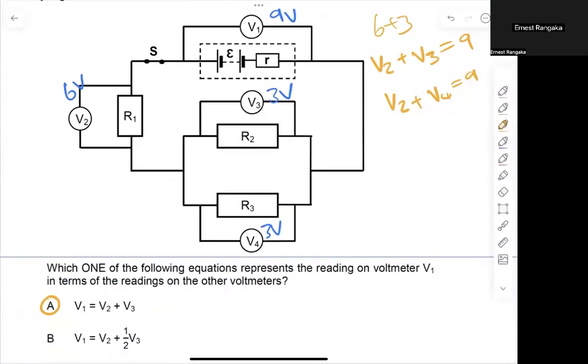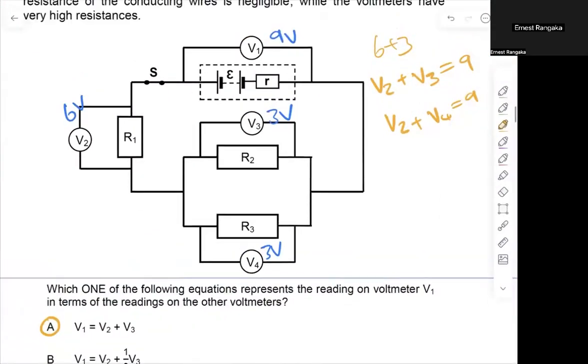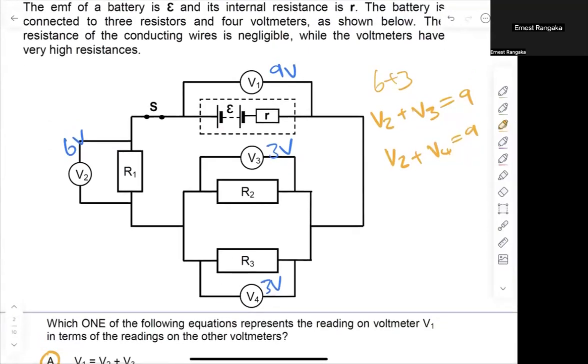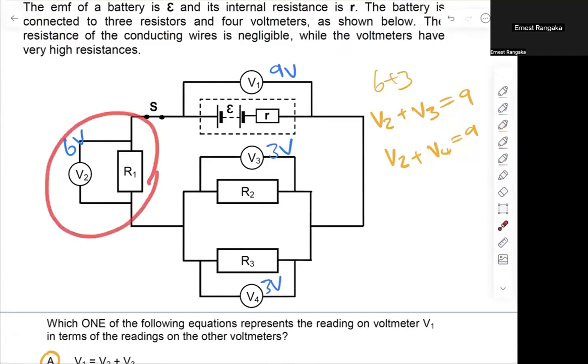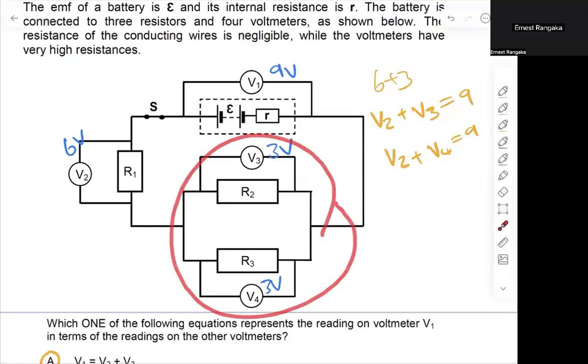So remember, like I was mentioning earlier on, the 9 volts is what my battery can push out. The first resistor here uses a certain amount of that, right? When I get down to my parallel component, that is going to be using something else completely, and then we go back to my 9 volts. How much of that is going to be used?